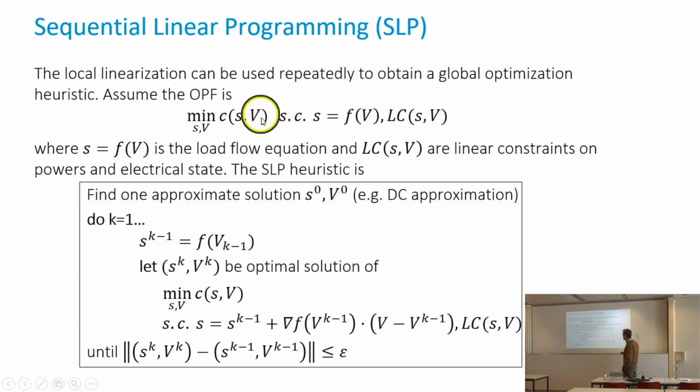And this may include, for example, a penalty for voltage magnitude being too far from the nominal value. We may or may not have a component here, if we can also linearize the voltage magnitude using the differential in a similar way. So this can become a linear function, or at least with respect to V, can be quadratic with respect to the cost here, to the injected power.